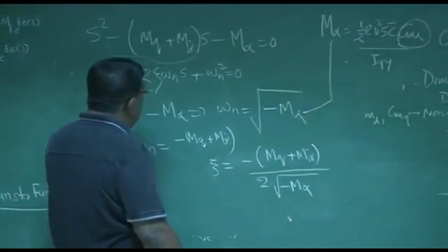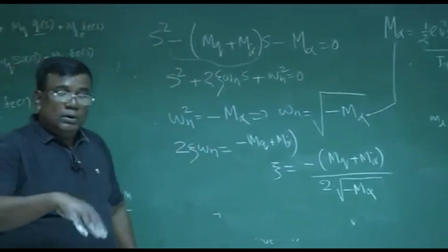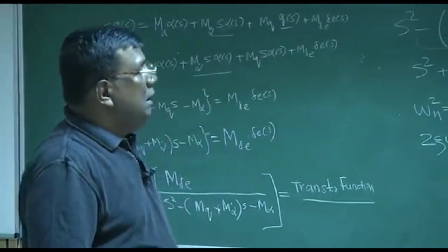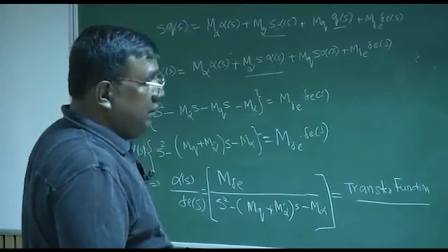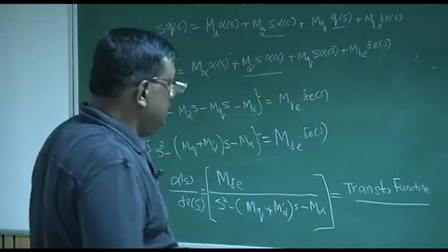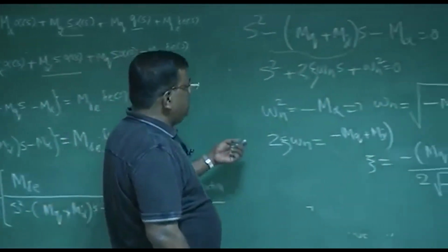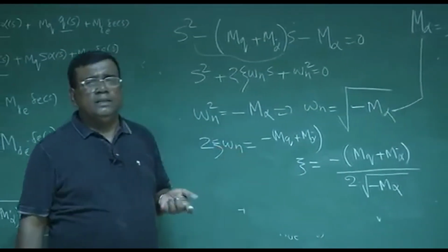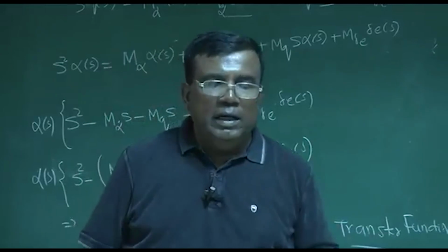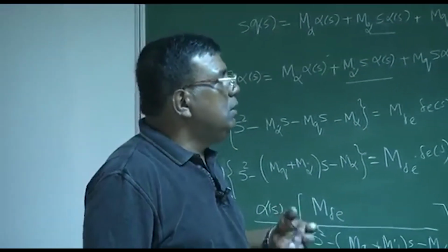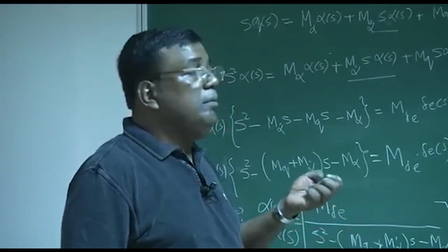But understand, this whole is for longitudinal motion, angular motion, right? In aircraft, you will find damping and natural frequency of different modes will be required. Okay? It only addresses this, which you will see is fairly close to a short period excitation. So today we have just made an attempt to understand a pure pitch motion and how to compute natural frequency and damping ratio.